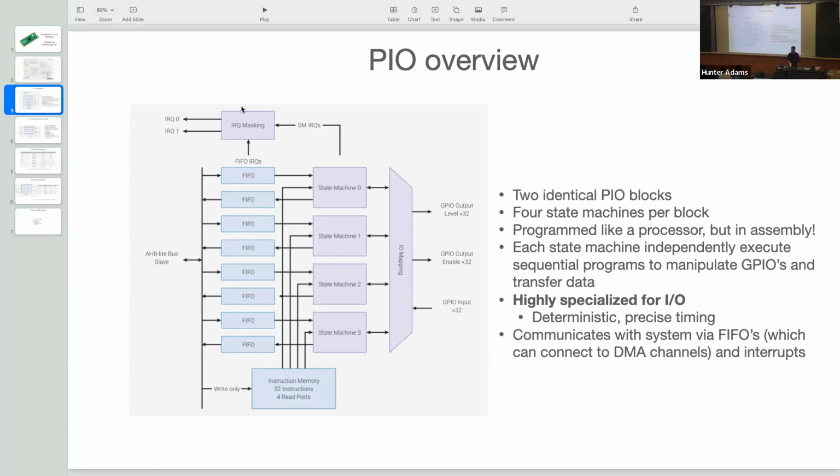There's 2 PIO blocks. Yeah. Why wouldn't the instruction memory be larger? That's a good question. I don't know. Bruce? So this is optimized for speed, means it has a limited address code read, and there's 5 addresses. The other question is, for a real application, let's say a new SPI channel, how many instructions does it take? 3. We'll look at an SPI implementation here, but 3 instructions.